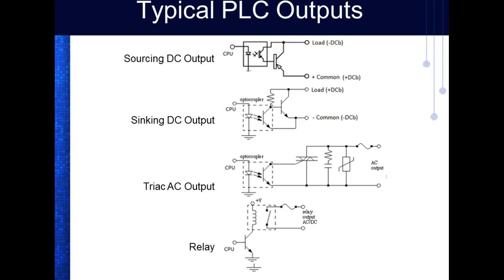You turn these on and they're on, you turn them off, they're off, which is relay, and this is relay. Which then we can put what on relays? Sinking, sourcing, okay. So when you've got a modular PLC, you usually don't specify either a sinking output or a sourcing output.